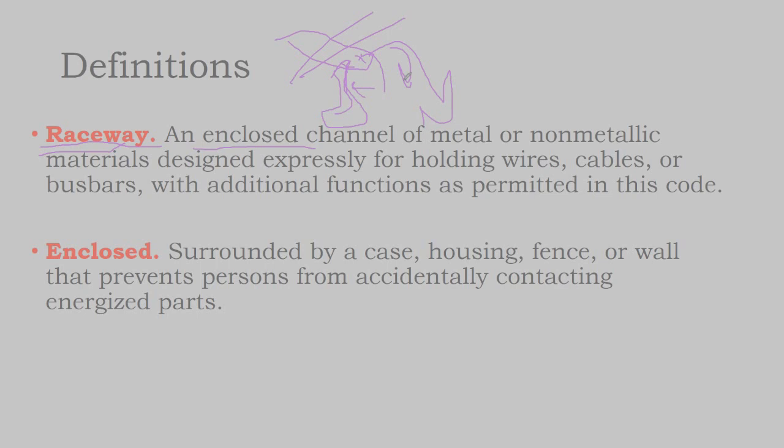But if they're not in that metal raceway, then how do we enclose them in a metal raceway? You might get a nitpicky inspector that would fail you unless you identify that, hey, we're going into the metal raceway as soon as we can in this system, but that might mean there might be a half an inch of space.